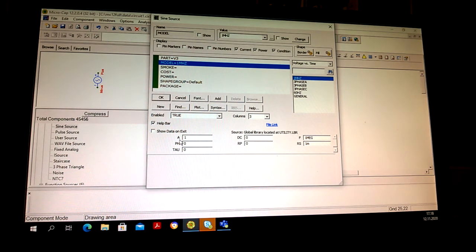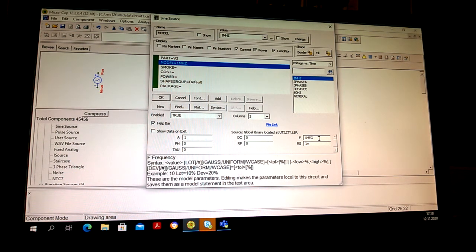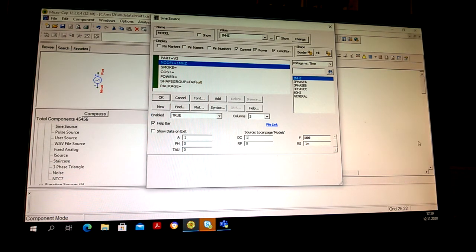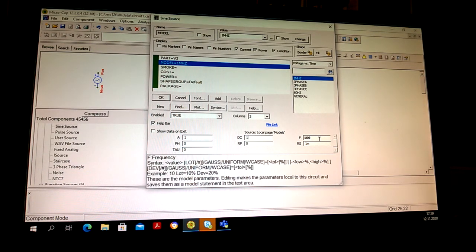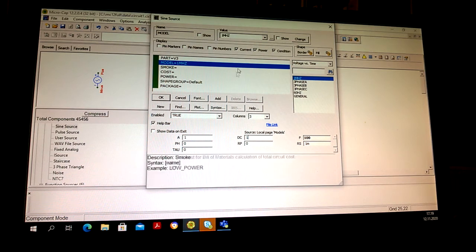Here is the amplitude, it means 1 volt. Here's the frequency, 1 megahertz. I think it's absolutely too much. I'm satisfied with a lot smaller frequency, and this is DC offset. You can put this above 0, under 0, so you can just put clearly volts here, like -1 or +1, whatever you want to.